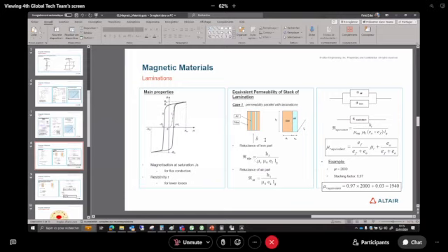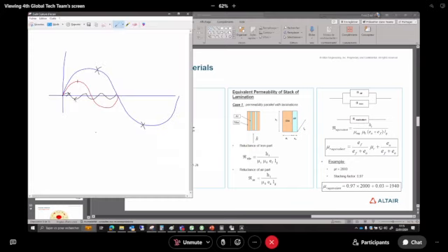So let's see how we degrade this initial magnetic BH curve due to the lamination. Once again, we make this lamination technique in order to reduce the eddy current inside. So let's consider a given stator. The stator will create a magnetic field like this, for instance, a 4-pole machine. So the magnetic field will move like this, and the laminations are like this.